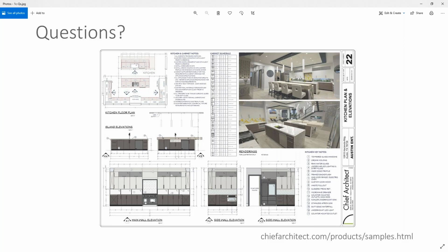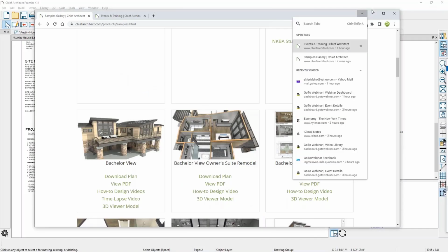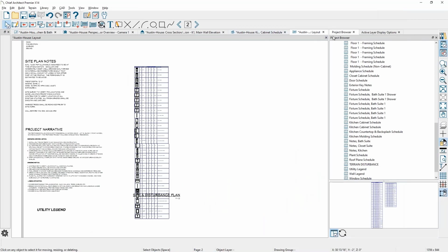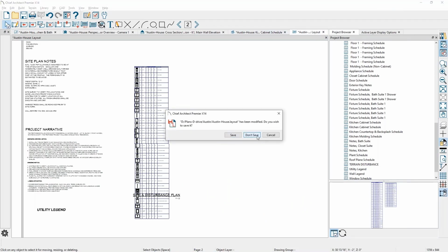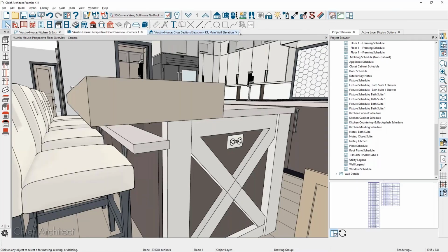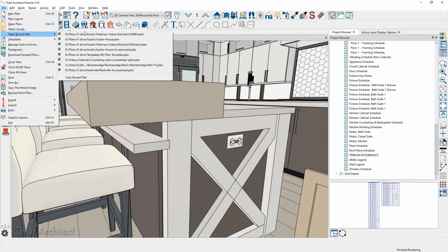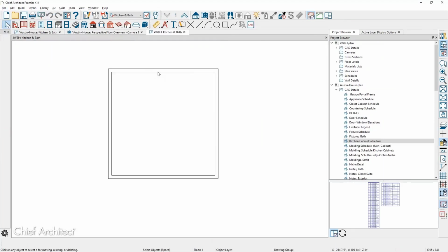When I put the two right beside each other, it seems to make the overhang on the 36-inch high cabinet disappear on that side. I'm wondering if there's a workaround. I've tried making the countertop disappear and going with a custom countertop, but then it makes the lower countertop disappear off that cabinet. It's a really strange thing.